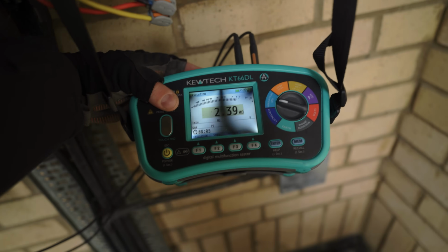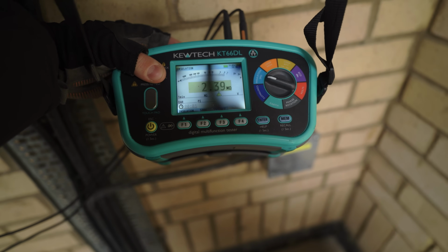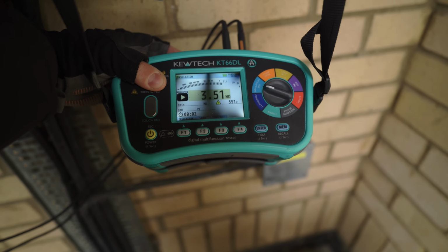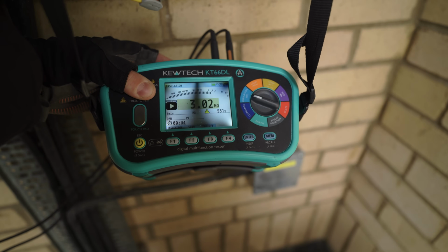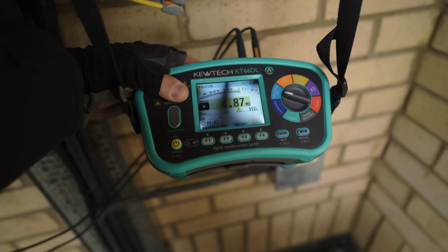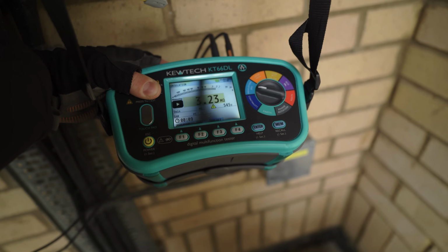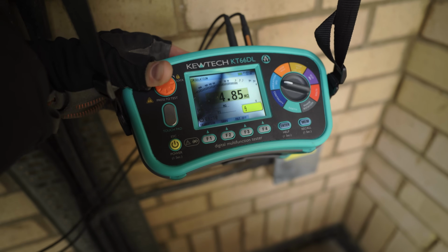Right, let's do it again. Yes, sir. 2 to 3 megaohms, lovely. 4 megaohms at points. 4.8. Cool, still looking good. Let's go get the last ones done. Get the last 1, 2, 3, 4 connected back up. Leave the 5th one disconnected because I think that's the problem. And hopefully I can get the circuit back on again, get some lights on. I think there'll be some faulty lamps, we'll have a count up, but it's looking good at the moment.